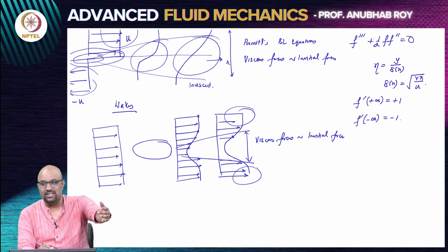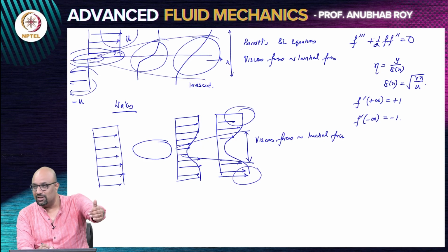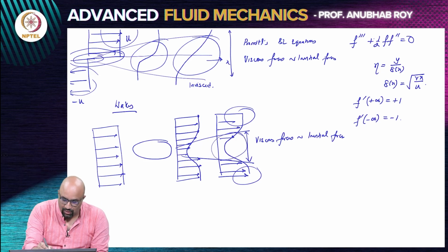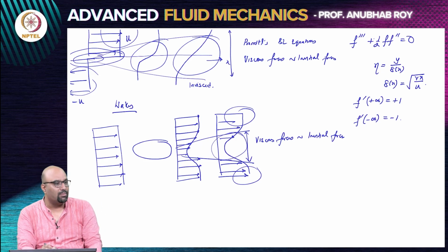Now if you are inspecting it significantly further downstream, there is a region over which viscous diffusion is going to become important. And you can study this problem exactly in the same spirit as a boundary layer theory approach. So whenever you are studying these problems, they are governed by an equation identical to Prandtl's boundary layer equation.